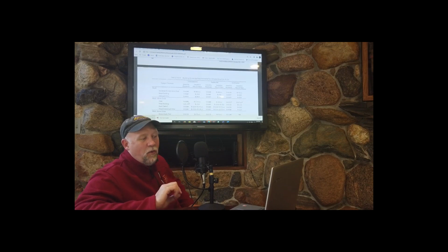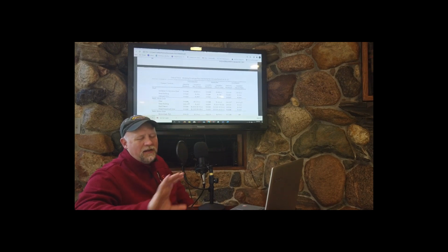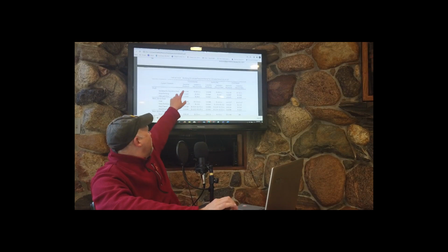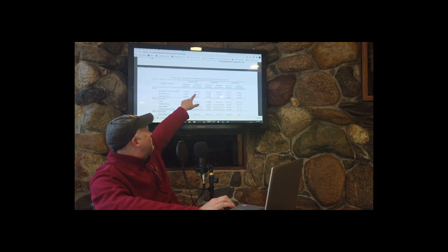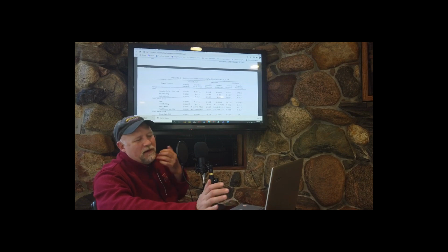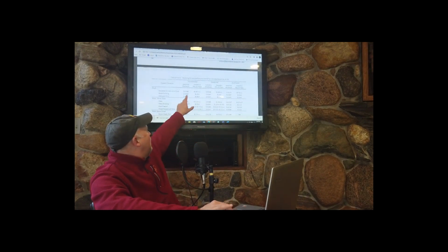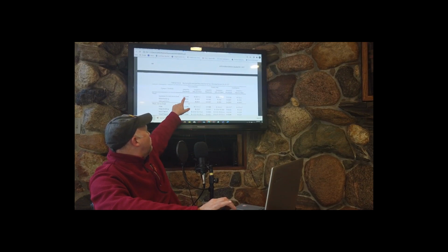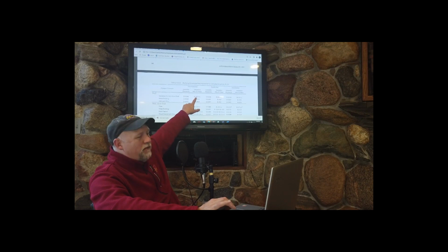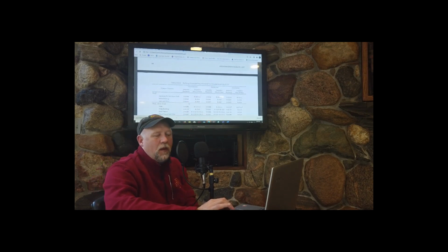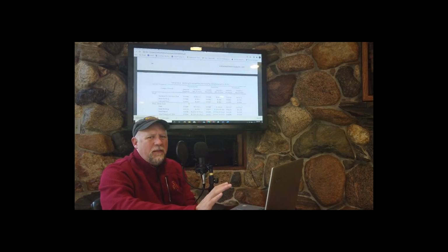All right, and that's going to be even more important when we look at walls. For roofs, this is probably not a big deal. We've just got R20 polyisocyanurate. You put it right down on top of whatever the structural deck is, and there you have it. Now, this is slightly better than this, and that's due to interior air films and that type of thing. But this is saying that you can't have any worse U value than this, and your R value has to be at least this R of 20, and then it has to be continuous. That's decent. I mean, it's not earth-shatteringly good, but it's pretty solid.